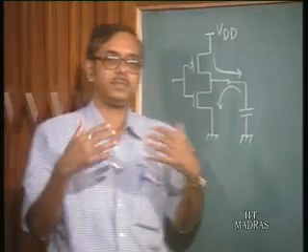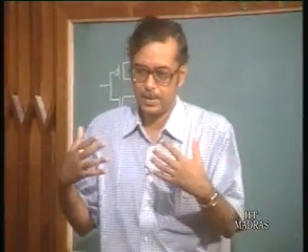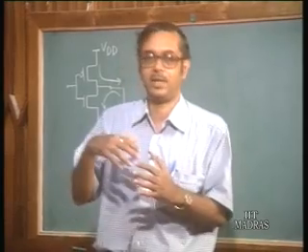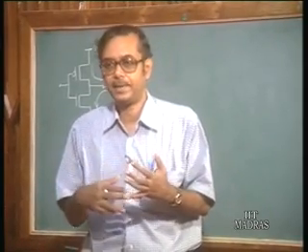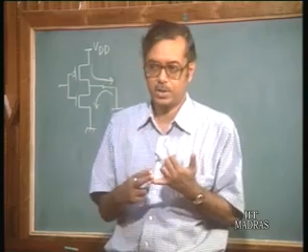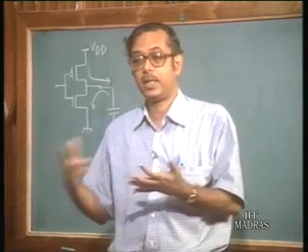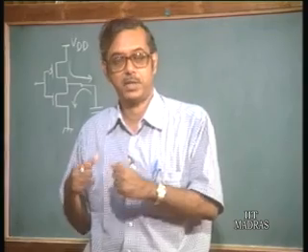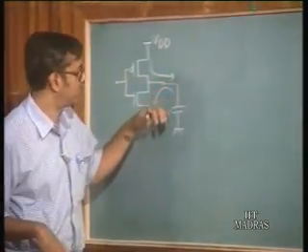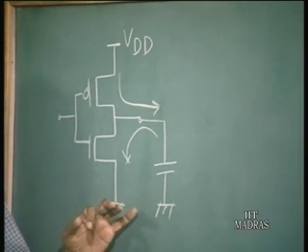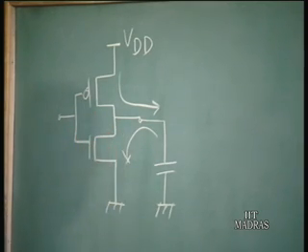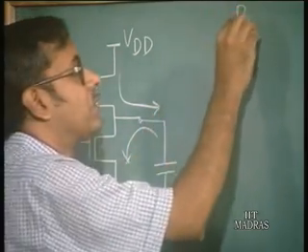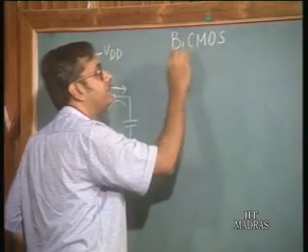Now, if we can have a logic family which derives the advantages of both, that is, on the one hand a logic family which has 0 static power dissipation, and on the other hand a very high current drive capability, that is, it can drive large currents to charge and discharge the output capacitances, then of course, using the bipolar transistor, it would be sort of the best of both worlds. So, that is what is attempted in the BiCMOS logic family, where you have